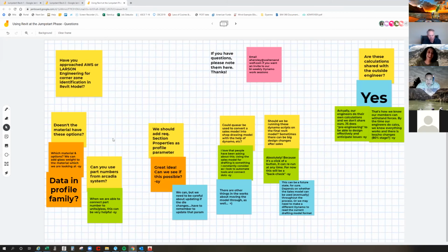I think the only place where it might throw a wrench into all that is when we have a wind tunnel study, and they identify high wind load areas. It could be at a balcony, that will be different, on a flat wall, and sometimes it's at a lower level or the upper levels of a corner zone, and they may expand that corner zone where it's a higher wind load.